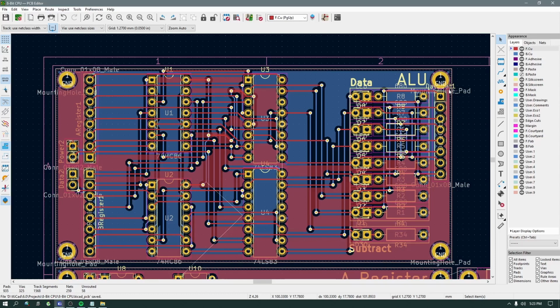For example, to subtract B from A, the CPU first gets the data from A and B, and it sends those numbers over the wires in binary. The control circuit will send a 1 on the subtract line, and this will tell the ALU to be in subtract mode. Then, the output of this operation will be displayed on the LEDs. This output number will also be stored in the A register for the next instruction in the program.